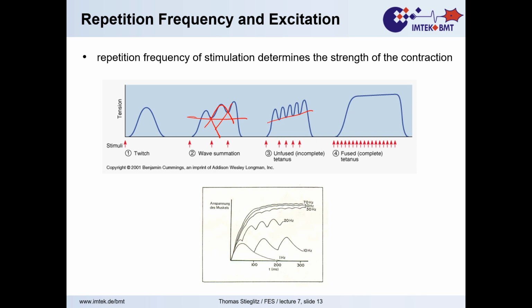And that would mean for stimulation, if I go close to the chronaxie, let's say 200 microseconds, I would have the cathodic phase 200 microseconds. I could take the anodic phase 200 microseconds. That's 400 microseconds. With a 20 milliseconds period, that will mean that 19.6 milliseconds is the pause in between.